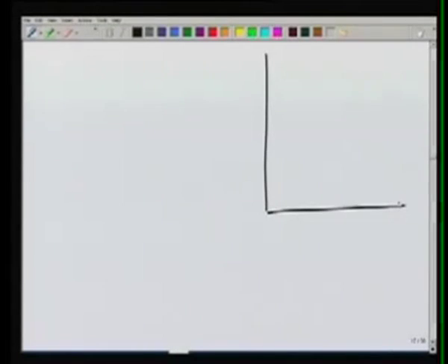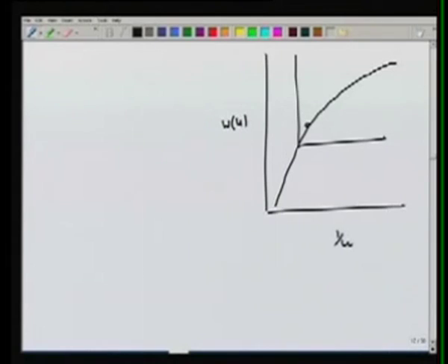So let's say that we have matched the type curve. This is 1 over U versus W(U), which is a fixed curve, and let's also say that we have matched the data by shifting the axis here. And now we want to find out the values of S and T. We can choose any point on this graph.